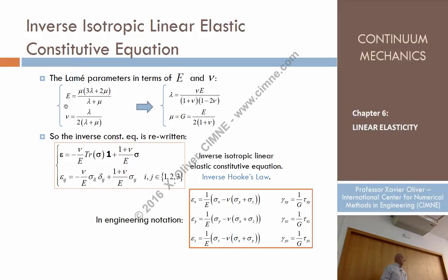So that is what we do with the two new coefficients. That is already familiar to you, right? This is the Young modulus. That is already familiar to you, the Poisson ratio. So now they appear in that equation, like just some appropriate change of variable, defining them in terms of lambda and mu, and of course these equations can be inverted and define lambda and mu in terms of E and nu.